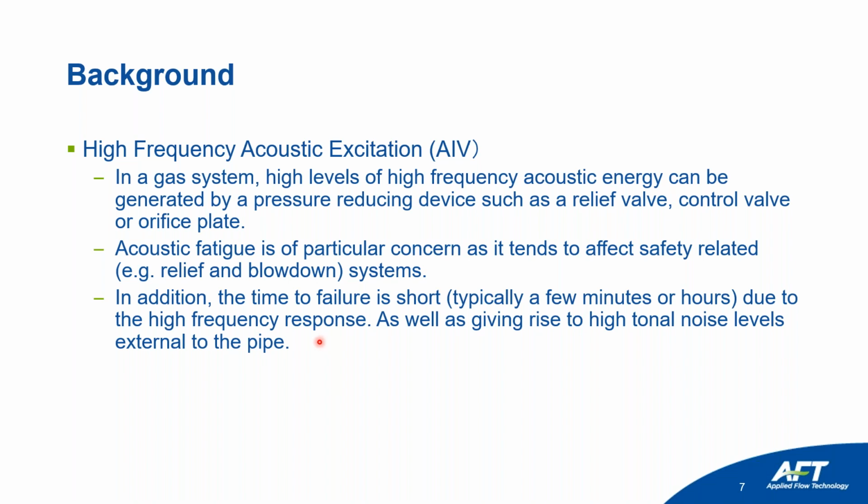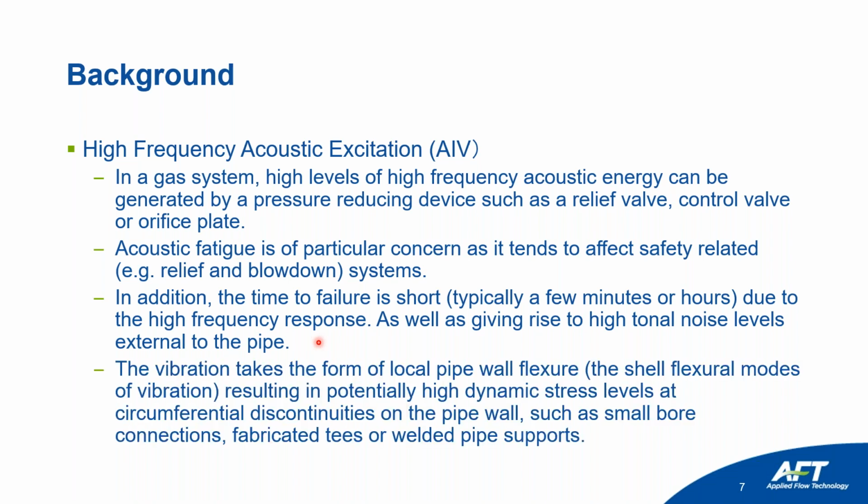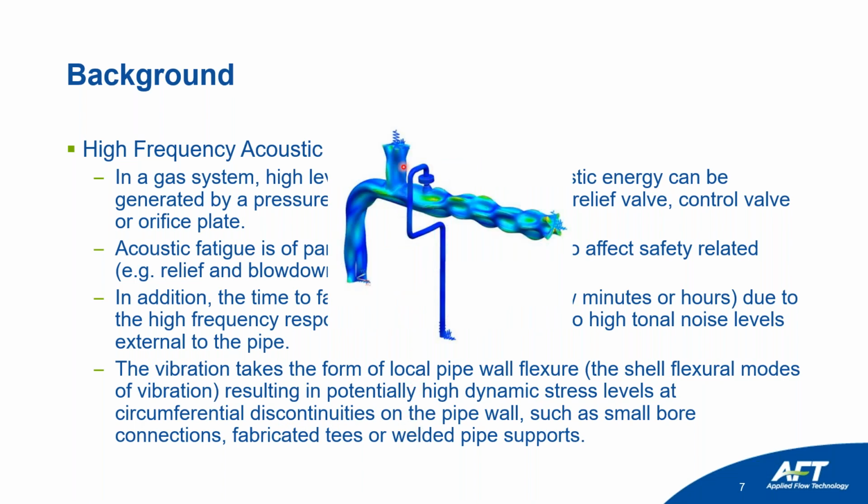operator, according to OSHA. So what happens is the vibration takes the form of a local pipe flexure, resulting in potentially high dynamic stress levels at the circumferential discontinuities on the pipe wall, such as small bore connections, fabricated Ts, or welded pipe supports. We have an example in the graphic of a relief valve opening that creates a high acoustic vibration.